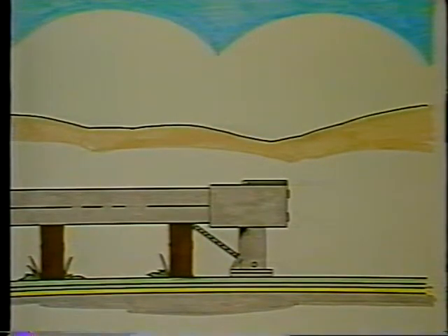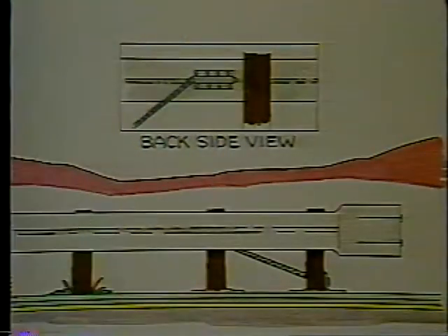To allow for this momentum slowing action requires a finely tuned BCT system, the first post of which will shear off at a pre-planned point where a hole has been drilled in the wood post system, or where a slip plate has been installed if the system is supported on steel posts. After being hit downstream from the terminal, rail strength of the system is maintained by tension in the cable.